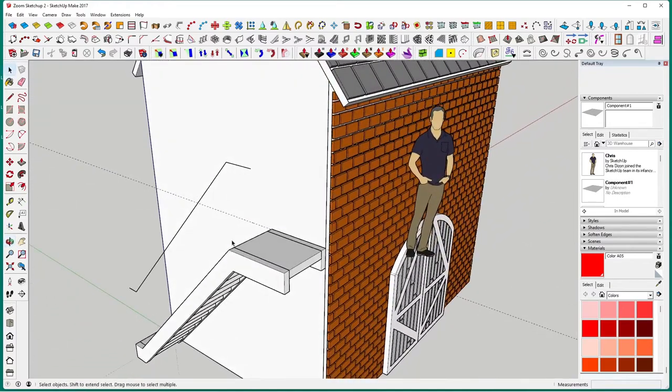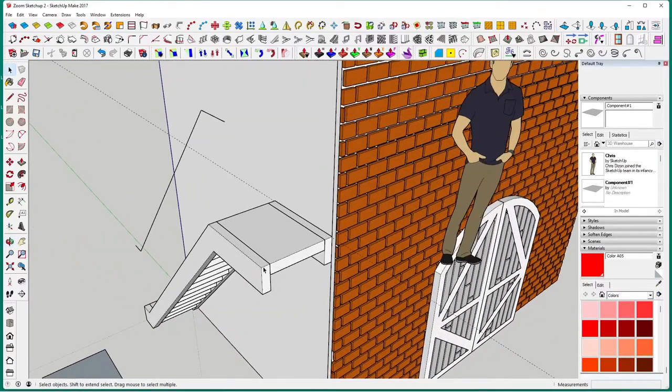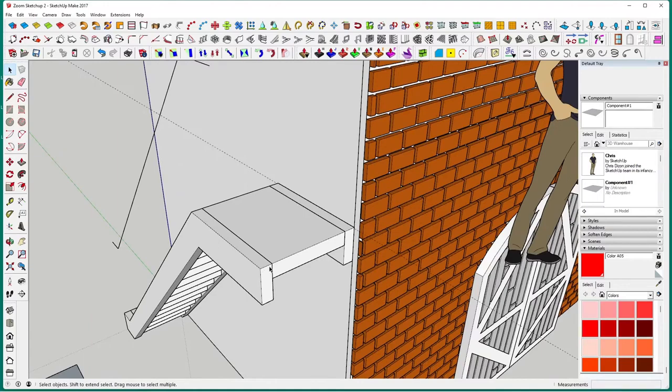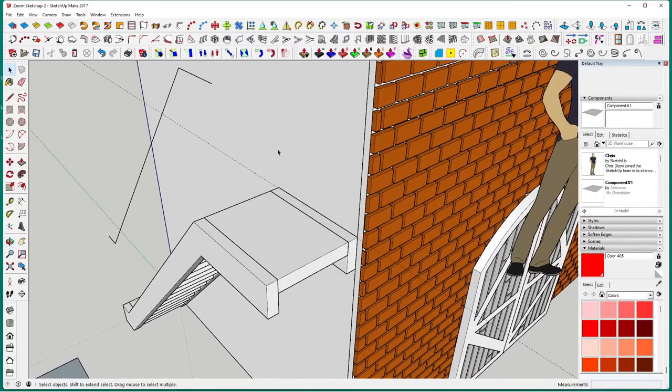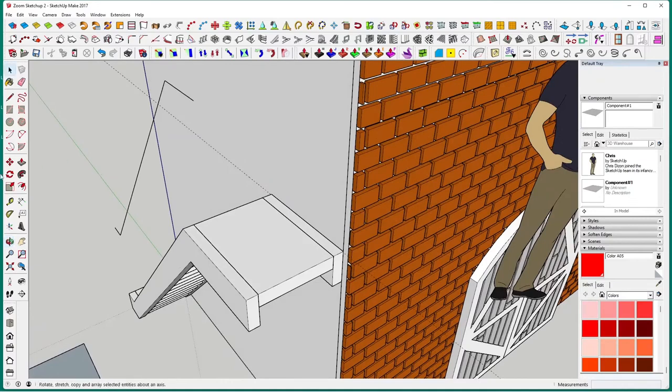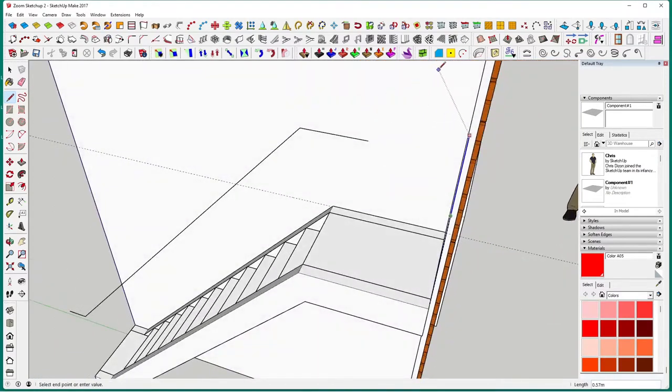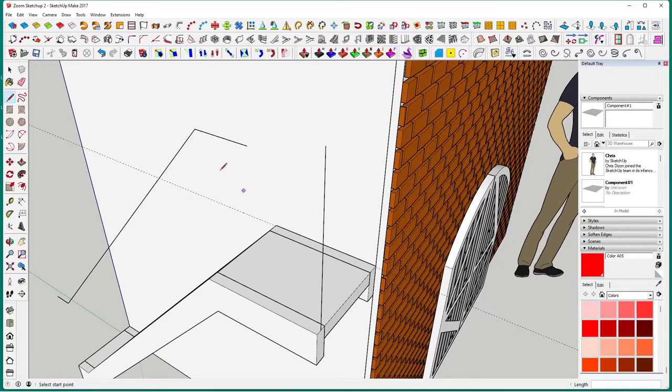Now this handrail goes down the middle. I don't know what they call it, the side bit, the riser. Anyway, what we need to do is draw a line up here so we can connect a handrail that goes all the way around. So pencil, pick the midpoint of the group, click, constrain it with the up arrow, which takes us up the blue axis. Just go past where the other handrail is. Escape. So now we've got a reference point.